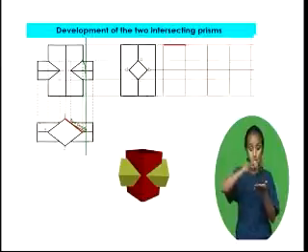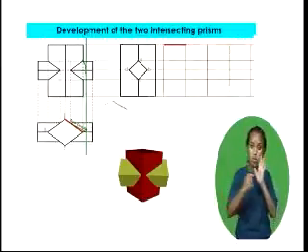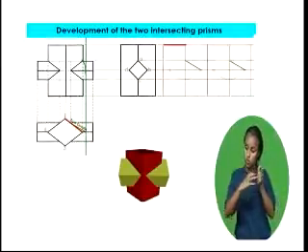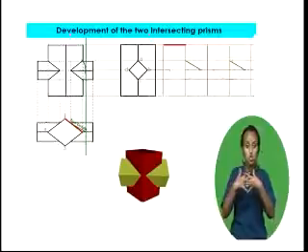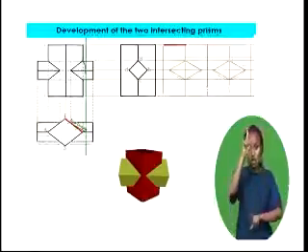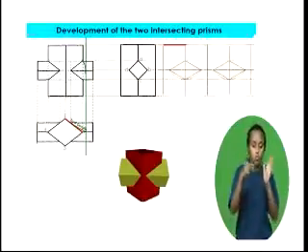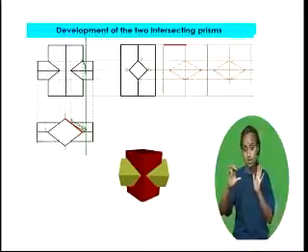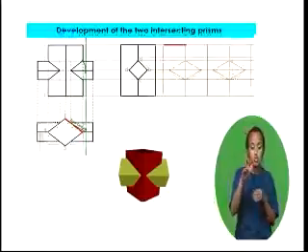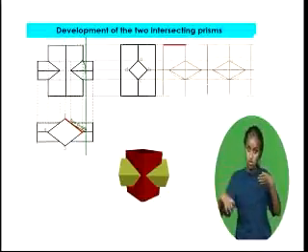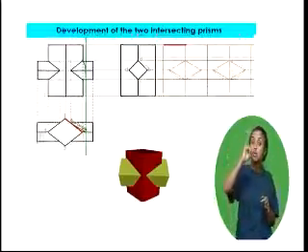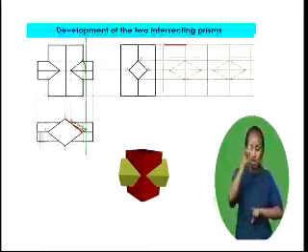Project the piercing points A, B, C, and D from front view onto the development to intersect corresponding lateral or vertical edges and establish the line of intersection. That means points A and C lie on lateral edges whose true distance can be measured from edge 3 of top view and transferred along the stretch out line each side. Connect the piercing points to complete the line of intersection on the development.